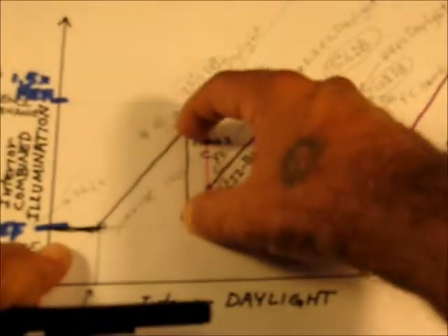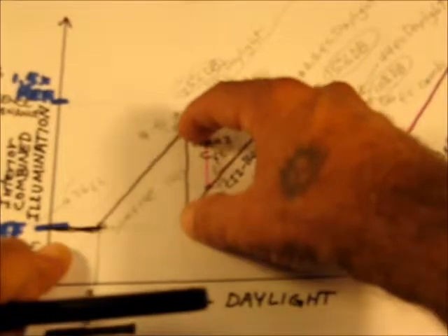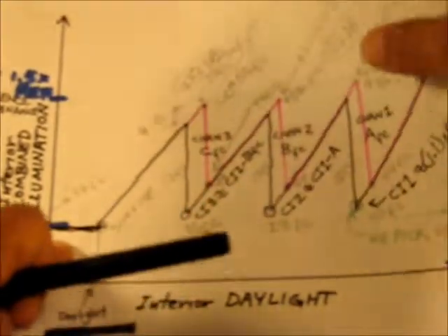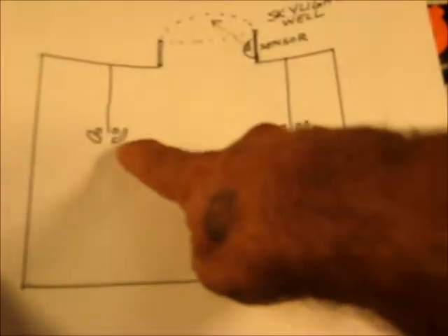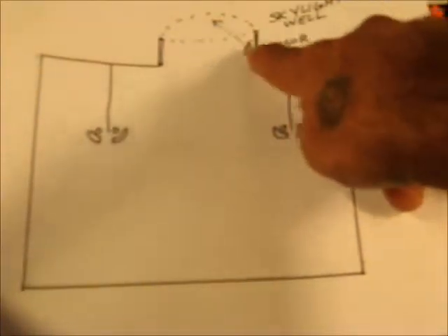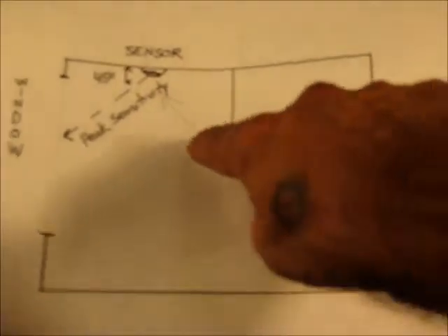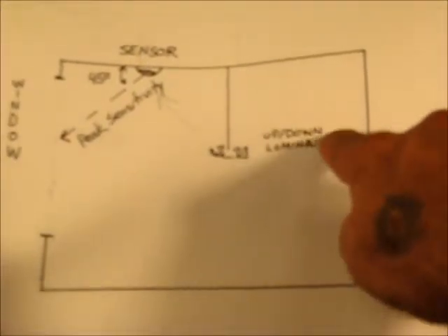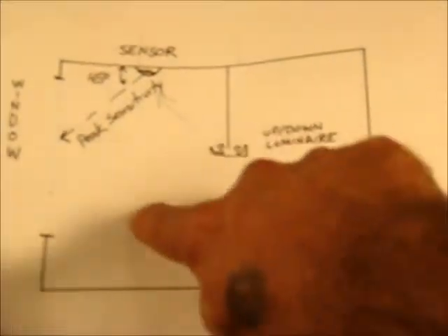And we're going to be shifting this controlled lighting up and down, if you will. Our requirement for minimum deadband depends on how much of a stage of controlled lighting hits the sensor, which is theoretically only looking outdoors. When one of these luminaires turns on, even if it's not up-down like this one, lighting will bounce around, it'll reflect off the window, and the sensor will see it.